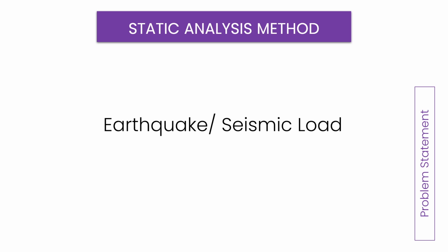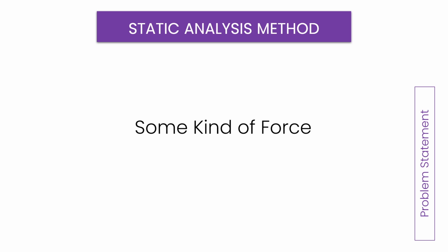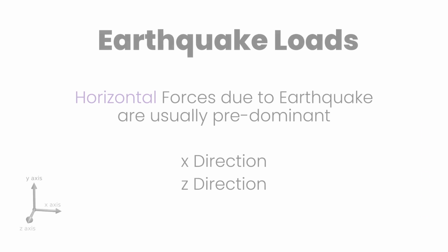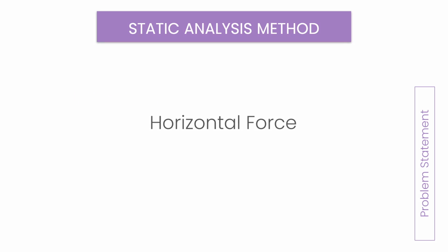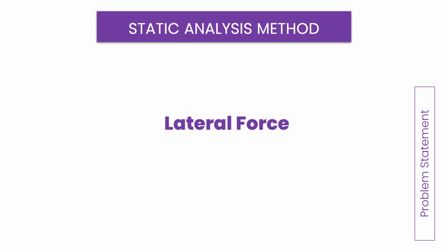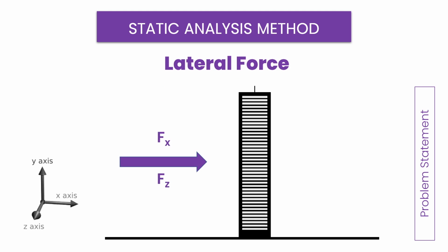Now, what is load? Load is basically some kind of force. And if you remember a few slides back, I talked about the concept that when it comes to earthquake, only horizontal forces are the predominant forces. So all in all, we are trying to calculate what is called a horizontal force, or in engineering terms, a lateral force. So this is what we will be trying to calculate. A lateral force would be a force in the X or the Z direction. So this is going to be a horizontal force. Now we have some understanding of what we are trying to calculate. Let's go on to actually calculating it.